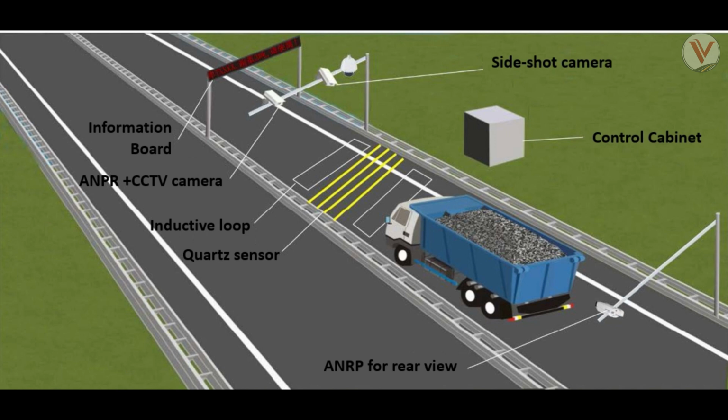Vehicle license plate recognition uses HD cameras to capture vehicle images for license plate number recognition. When the vehicle enters the ground loop, that triggers the HD cameras in the direction of the front and rear of the vehicle to capture the head, back, and side of the vehicle, and at the same time, with the fuzzy recognition algorithm, to get the license plate number, license plate color, and vehicle color, etc. The HD camera can also assist in detecting vehicle type and driving speed.